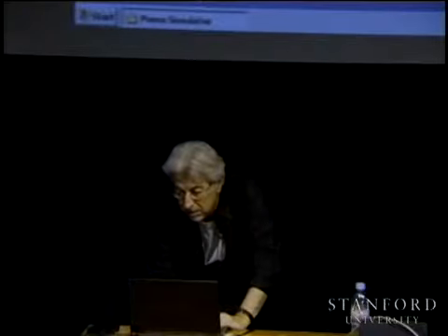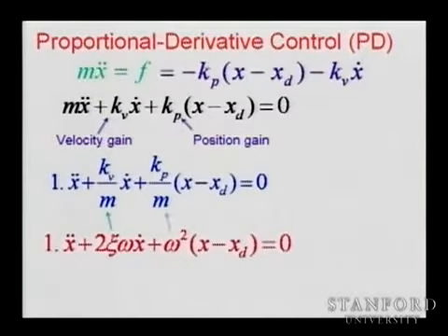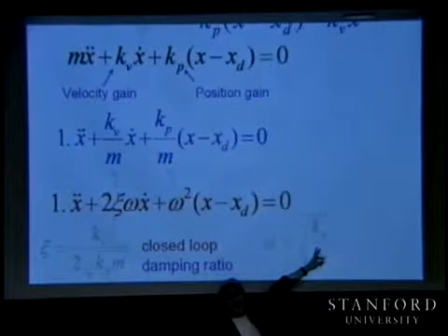So this Kp we have here cannot go too high. We want it as high as possible to increase what? What does it do when Kp is high? Disturbance rejection, because errors coming from dynamic coupling from other links will be rejected. It's stiffer.